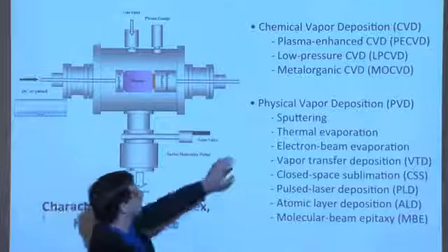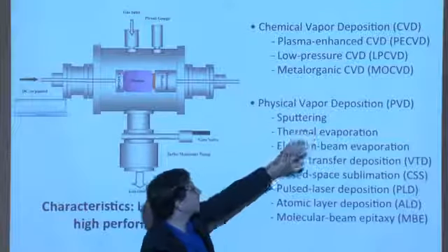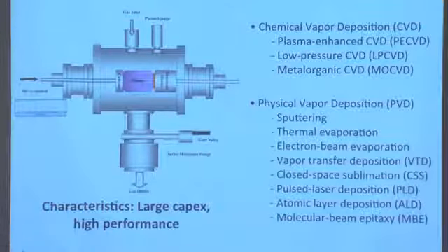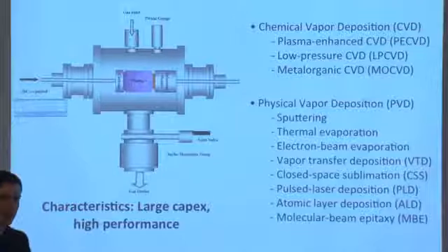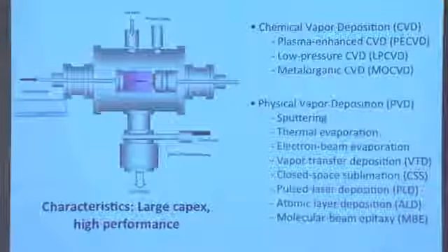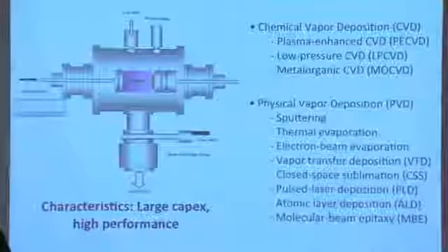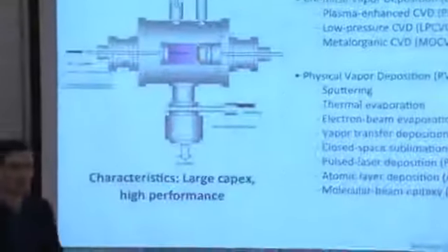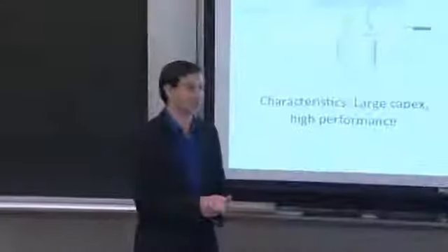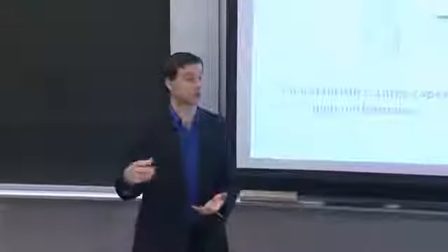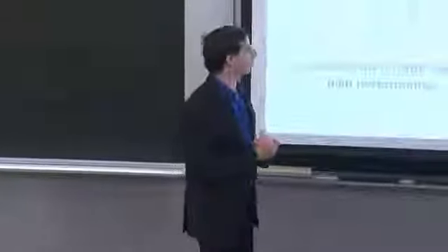The chemistries involved in CVD processes can be quite complex, and the reaction process itself can be very difficult to master. So you might have some friends who are involved in spectroscopy, shining lasers at their system and looking at the absorption lines and trying to figure out how these molecules are evolving between when they're inserted into the chamber and when they actually wind up as your film. Because understanding the chemical reactions that take place is key to really controlling the CVD process.